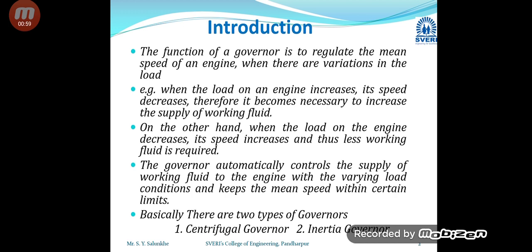Now the governor does all this activity automatically, and that is by means of mechanical linkage only. The communication is done in a mechanical way, and the increase or decrease in load is sensed by these mechanical linkages, and accordingly the working fluid is increased or decreased.